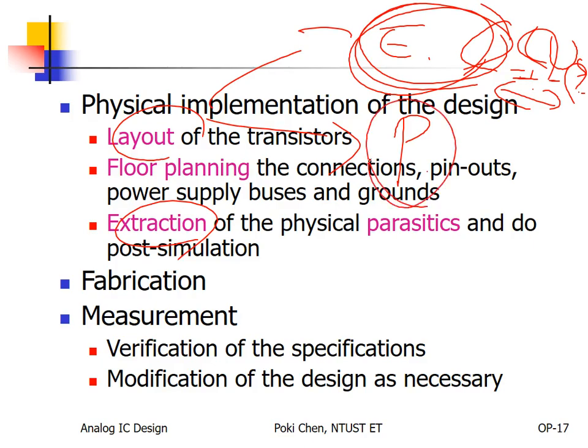So what is the difference here? Parasitics. With parasitics means post-simulation. Without parasitics means pre-simulation. Never mind, you simulate the equivalent circuit of your layout or the original circuit, they should be exactly the same if there's nothing wrong. So please keep this in mind.